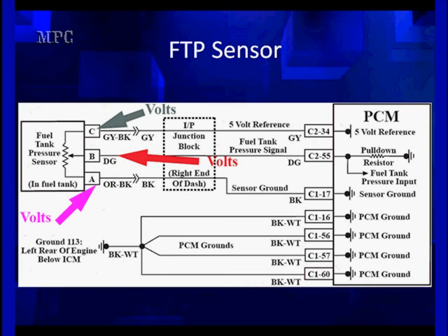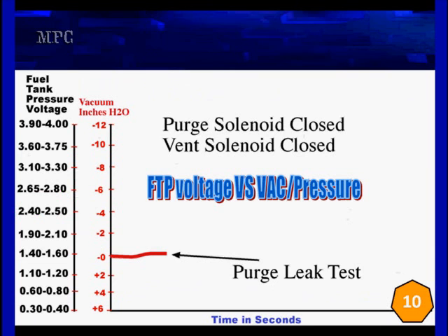We're going to control it. We're going to do our standard testing. If we don't think it measures accurately, we're going to come in here. We're going to measure voltage, measure ground, measure the signal. If volts is good, if pin C reads 5 volts, if pin A reads under 0.5 volts, and we cannot read engine off vacuum to be sure we can remove the gas cap accurately, change the fuel tank pressure sensor. It's that simple. So we've verified our pressure sensor. We fixed the ones that are broken.